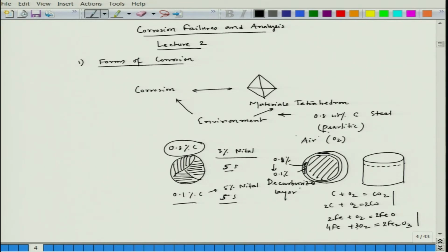So, it is obvious that the pearlite content, as you saw in the last lecture, in a 0.1% carbon steel is mostly ferritic, and pearlite would be along the grain boundary only. So that time it will look whitish in nature, because pearlite, since it has ferrite and cementite, looks a greyish color rather than ferrite. The ferrite looks a very bright color under the optical microscope. That is why it looks like a white layer.